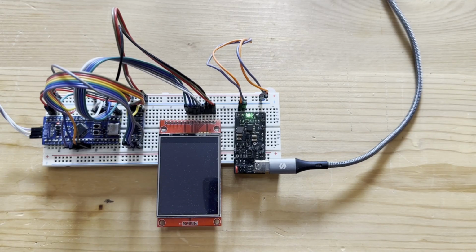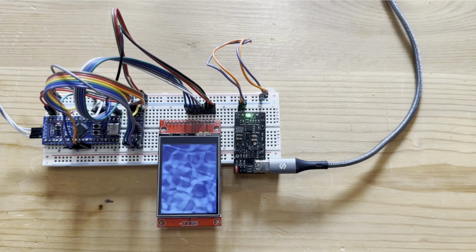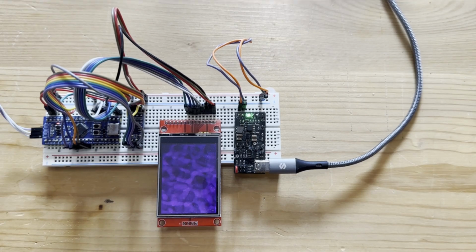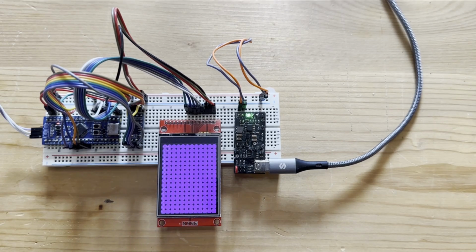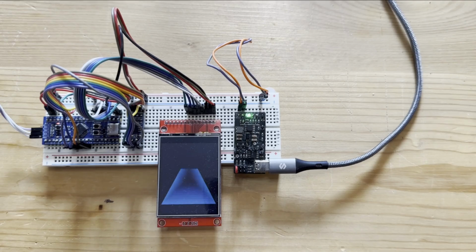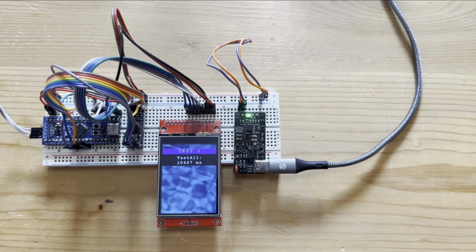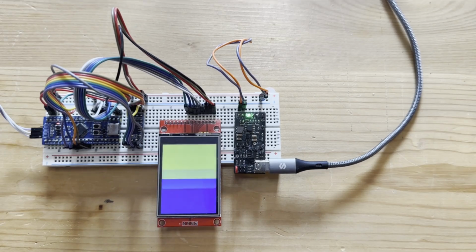Okay, we have seen that, having available an external loader corresponding to our project configuration, we can in a really easy way handle pictures to draw on a display. That just setting up a simple configuration of linker and of the project parameters in CubeIDE. I know you say that, handling SPI Flash memories can be simple using external loaders.